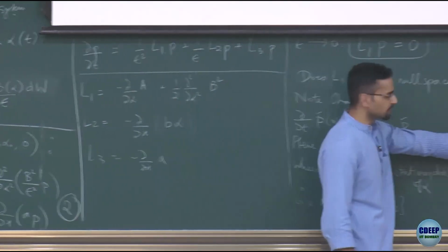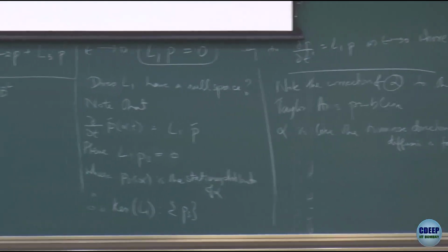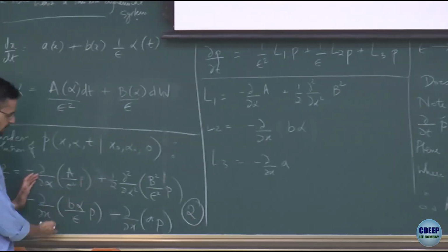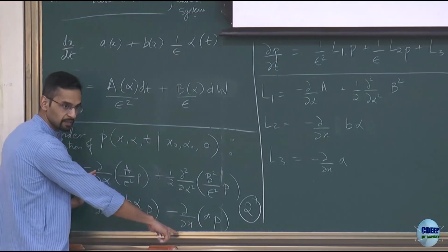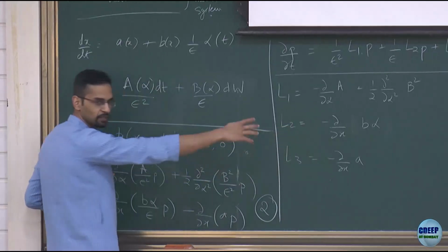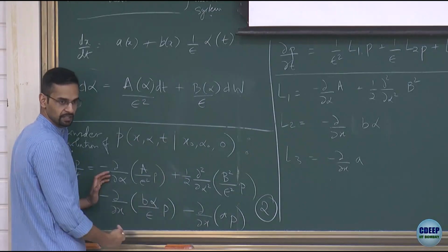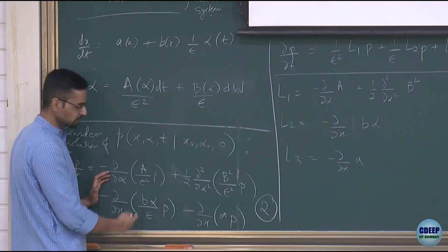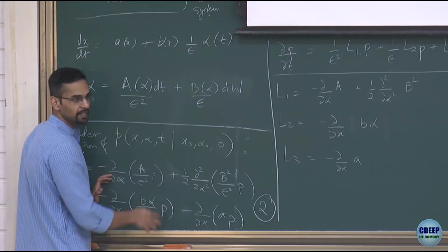You see the same thing is there here, right? Alpha is like the transverse direction. I have a PDE in alpha and X. X is like the slow advective direction. In the pipe, remember X was the slow direction along which things were advecting slowly, and alpha you can think of as the fast radial or transverse direction. In that Taylor-Harris problem, there was only diffusion, and it was physical diffusion.